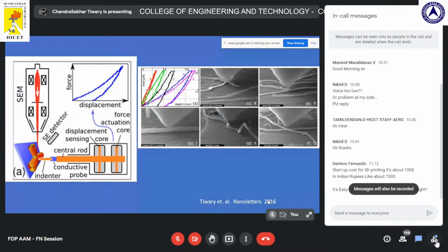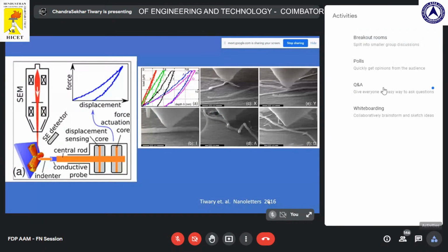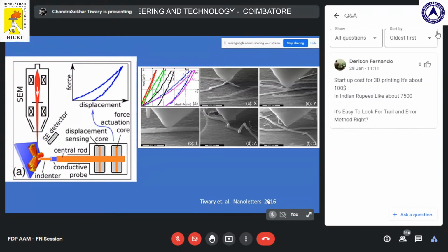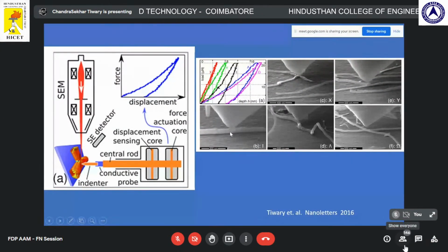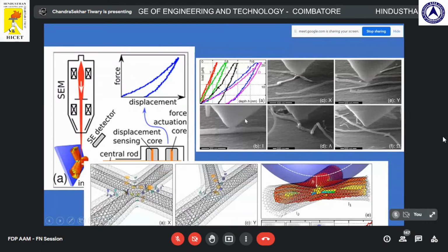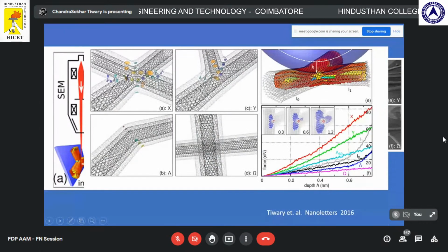Okay, sure. So carbon nanotube was one of the initial nanomaterials which people were excited about. When you take a nanotube and do mechanical property measurement, what you see is that the flat nanotube is fairly softer than one with a complex topology like X geometry, Y geometry, or interconnected carbon nanotube geometries, which were much stronger or stiffer compared to a simple nanotube. The reason was the topology in the nanotube. Remember, this topology means curvature and this kind of complexity in shape, which is because of atomic scale defects and atomic scale bending, right? And the MD simulation does show that.